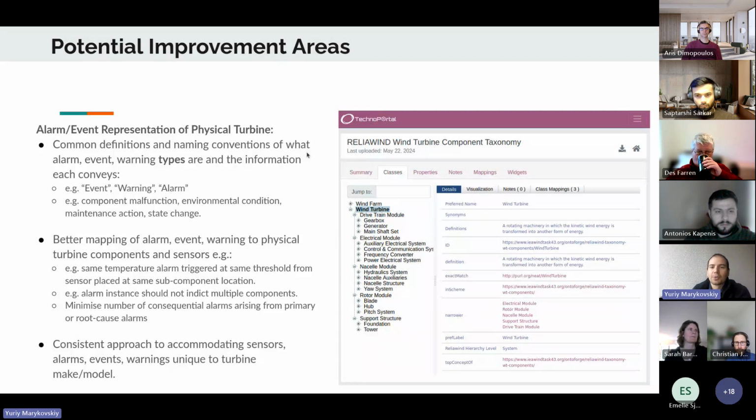We had to actively find people who were working on this project to get this taxonomy published in machine readable format, so that people can actually see, oh, that is how you were calling things, how you were defining things. But currently, every time an FMECA analysis is performed, everyone develops their own new taxonomy. And then the problem is that the results become non-interoperable. You cannot port the results from one operator to another, because they would not agree, for example, that the rotor module is blade, hub, and the pitch system.